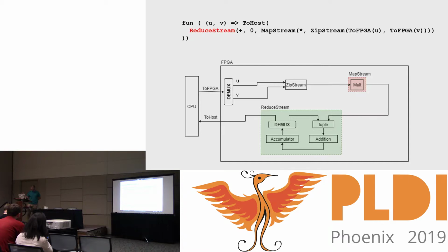So here you can notice that the hardware that we generate is not some von Neumann architecture, so we don't have instructions. We don't need to fetch the next instruction, then decode it and execute it. We really express the program directly in hardware using these data flows, connecting it together, using only the functions and the operations operating on the data that we need in the program. And this is the power of specialization that results in the performance and energy efficiency.